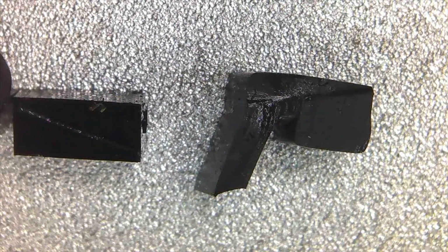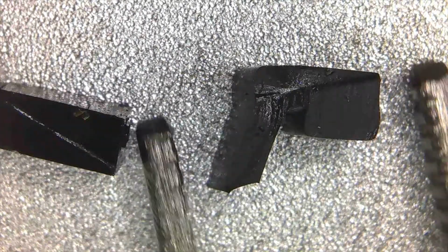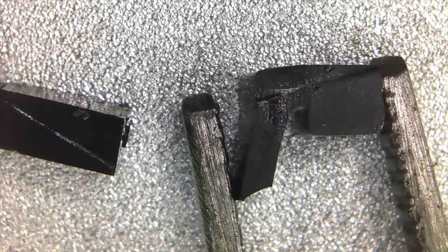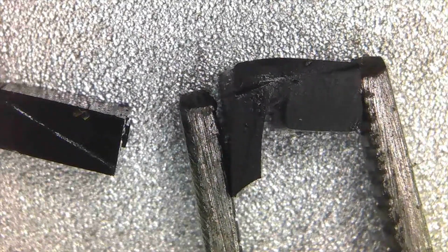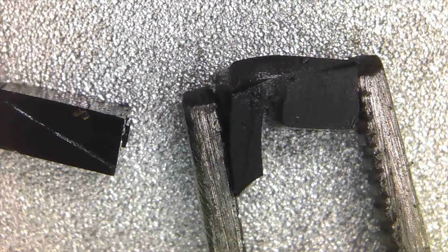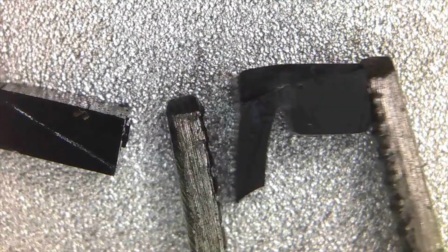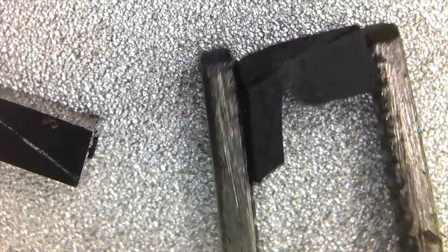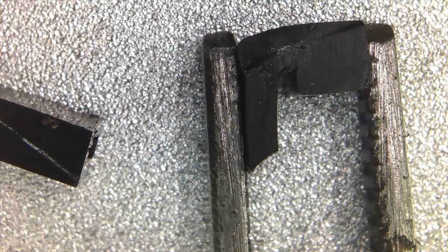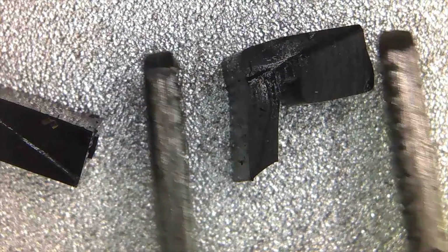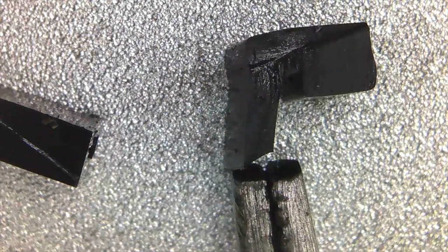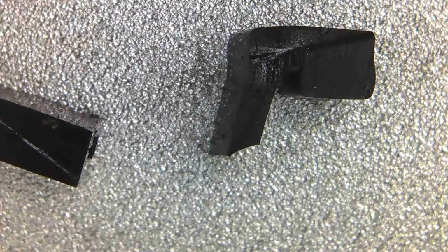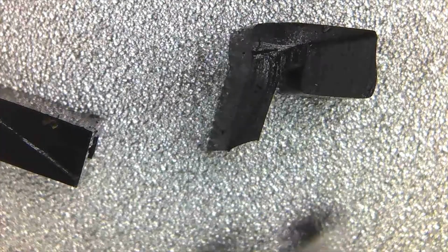Now, it does lead to another, I wouldn't call it an issue, but another characteristic of lip seals, which is that you can't just push the piston into the bore. You actually have to have a tool, or usually a seal protector, that is going to fold that lip in all the way around the piston so that it can go down into the bore of the drum. It's going to be almost exactly like a piston ring compressor. It's going to cause that lip seal to fold down so that it will slip down into the drum, because this one, since it's got such a long lip on it, tends to have more chance of being damaged.